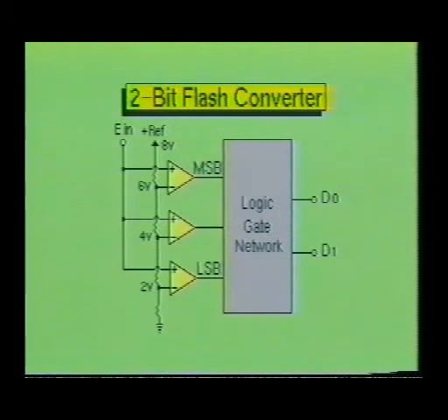Very few analog to digital converter circuits are as fast as the parallel converter. The conversion speed of this converter is so fast, it is often called a flash converter. The flash converter uses a bank of parallel comparators to process the analog input signal. One input from each comparator in the stack is connected directly to the analog input signal. The other comparator inputs are biased by a DC reference source through a simple precision resistor network. The resistor values are chosen so that each comparator is biased one least significant bit higher than the next one down in the chain.